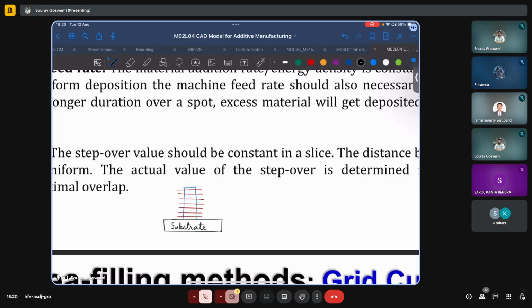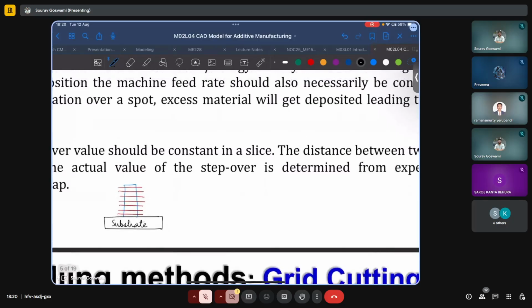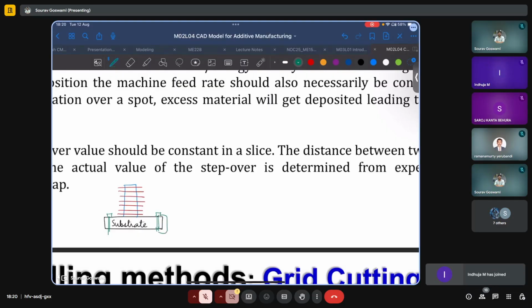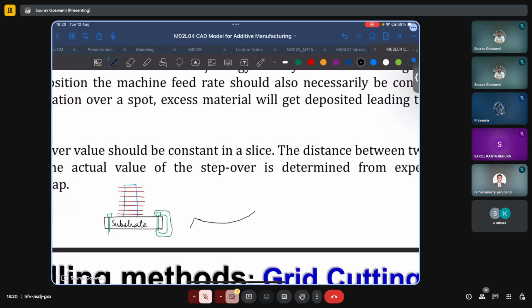Now, because of the high temperatures and the heat fluxes involved here, typically we would clamp it to the build plate, to the machine bed using some bolts, or even C clamps. But still what happens is, and what we notice later is that typically the substrate plate tends to warp upwards.